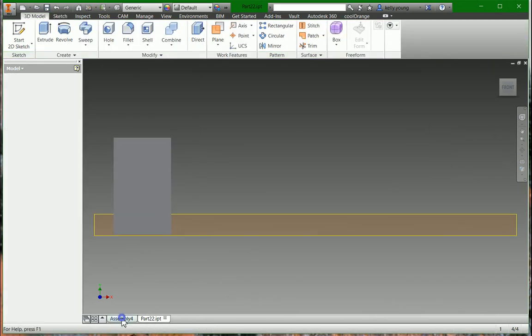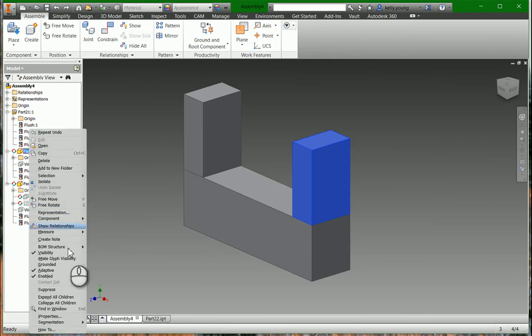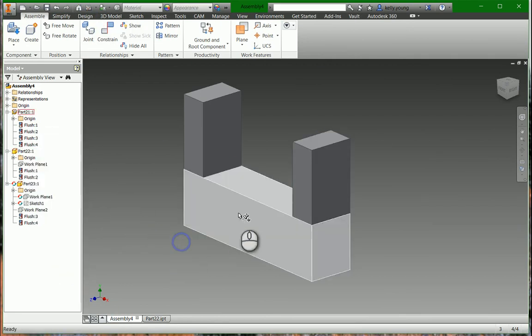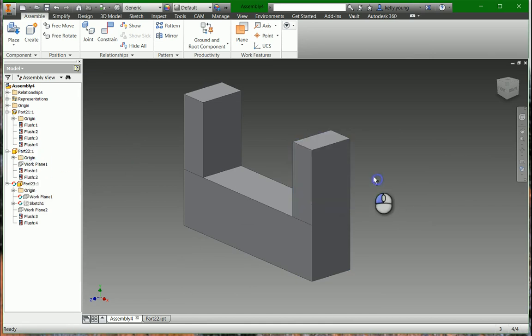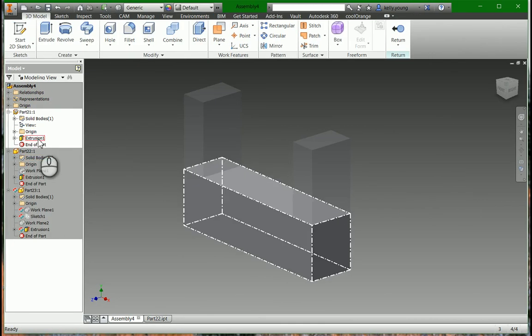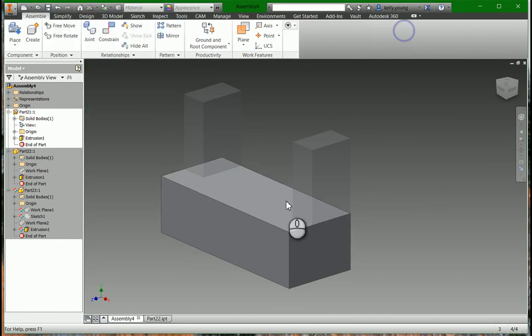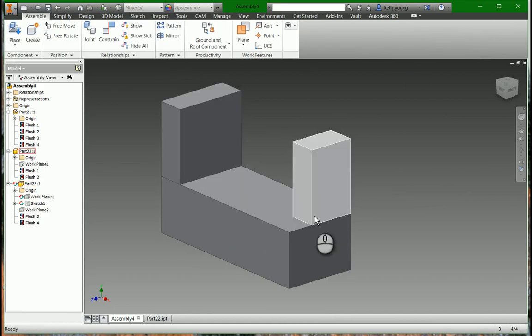There are some drawbacks to doing that, because if we come back into here and refresh the part, make it less adaptive, so this one, if we change to 8, this one doesn't follow and that one does. So it gives you an idea of where the adaptivity is, because this one is now